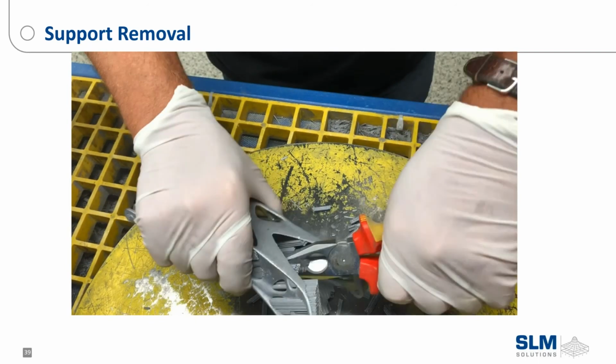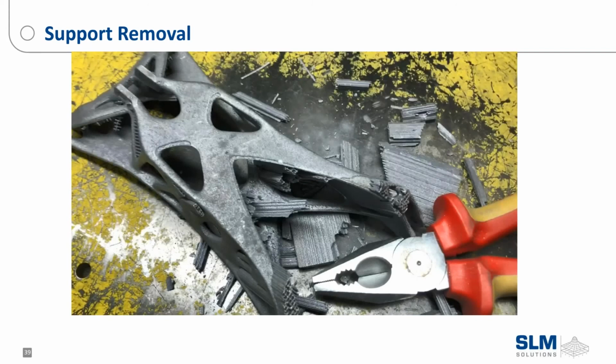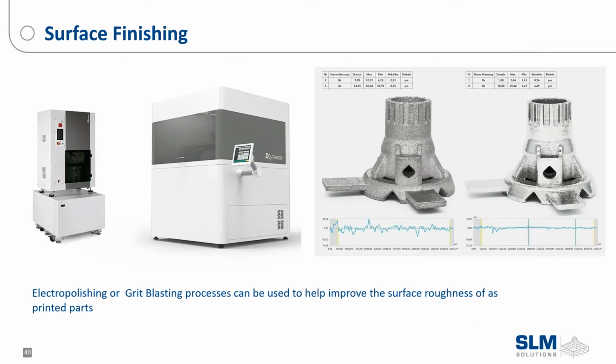Now imagine if this was titanium or Inconel or anything of that nature. That material would be a lot harder to remove. Not just hand tools snapping this off, but we're talking about using air chisels or die grinders, tools like that, to remove some of this material. And you see the material does break off.